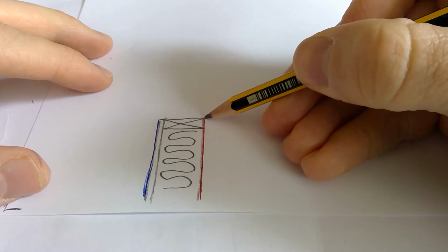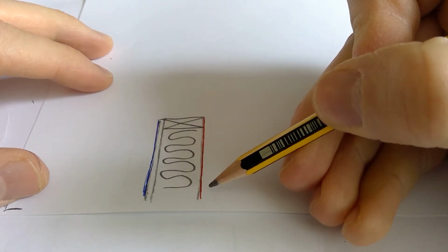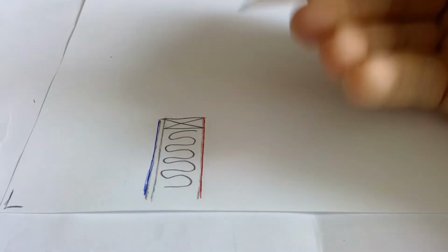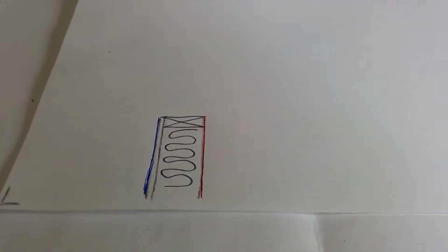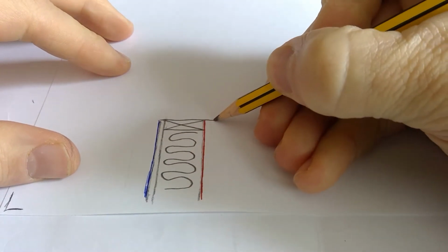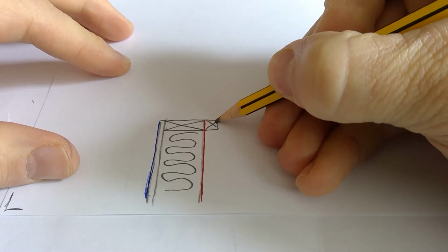Okay, now usually what we would draw here then is plasterboard in place on this side, but the book says that there's a service cavity. Right, so a service cavity, it says in the question that it is a 60 millimeter service cavity. So what I would do here is build out a 50 millimeter batten, one piece of wood nailed up to there.